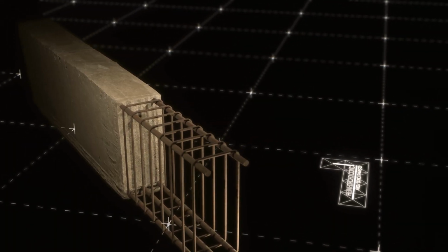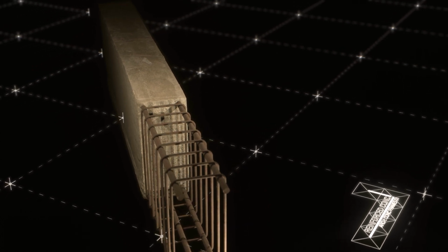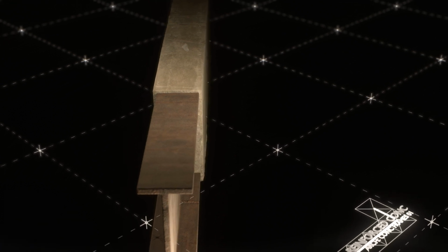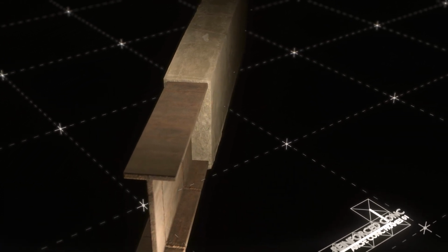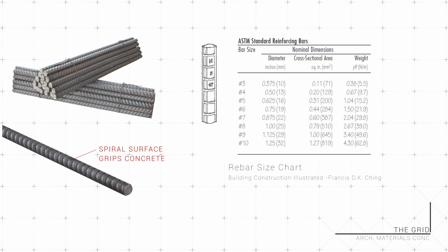steel-reinforced concrete. Reinforced bars, or rebar, are embedded within structural concrete members. While you could just put entire I-beams in concrete, and that does happen, rebar is less expensive than full steel beams and also easier to work with. Steel rebar is distinguished with spiral or ribbed bodies for added grip within concrete. The cylindrical bar sizes vary based on nominal numbers 1 through 10, each number corresponding to a different rebar diameter. Number 5, for instance, is 0.625 inches in diameter.